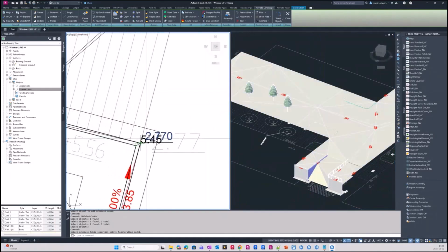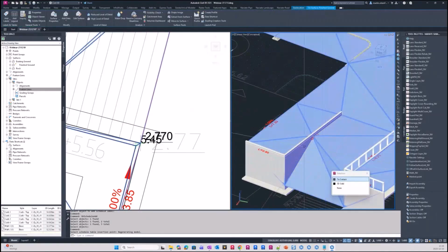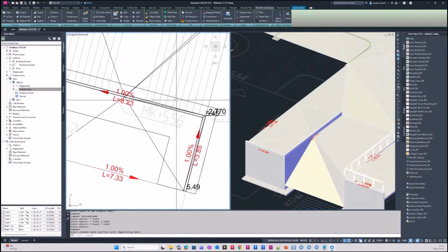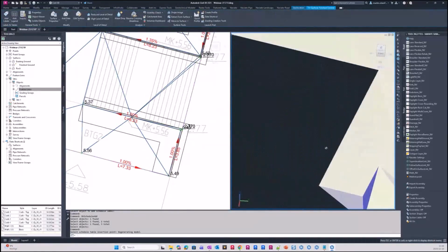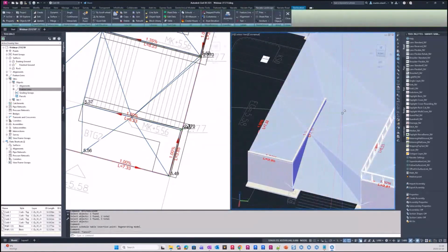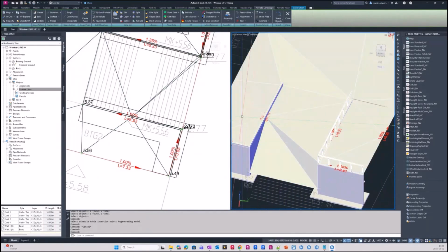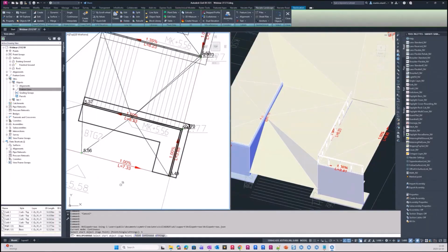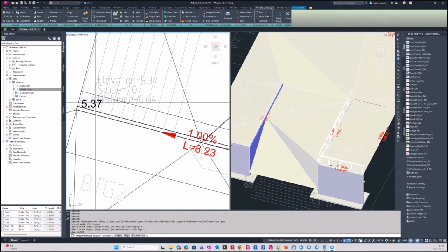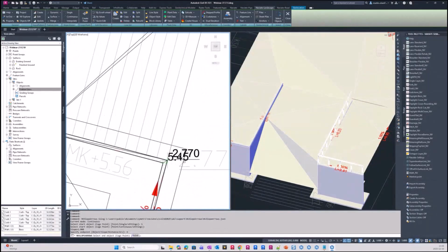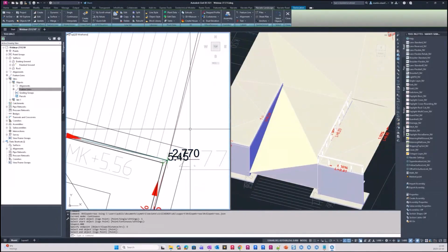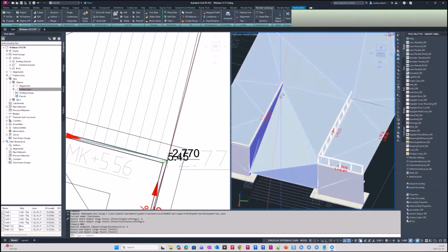And here you can also see why you should use feature lines when you're modeling surface. To get back to the slope arrows function, you can see here that the surface isn't really well triangulated because we got a high point here and a low point there. So here we need a line between those two. So I can just pick a single point, pick this point, go for object again, and pick this point. And now we can see how it breaks the surface.